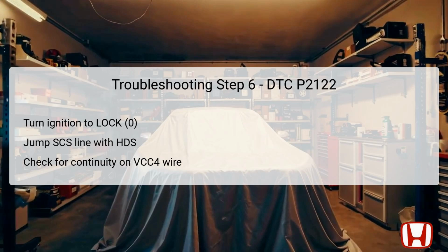Terminal A will be connected to APP sensor 6P, connector number 4, brown, while terminal B connects to body ground. Check for continuity between VCC4 voltage supply points, ensuring that the test conditions match those outlined in the diagnostics. If continuity is confirmed, it indicates proper function of the VCC4 wire, allowing for software update or PCM substitution, and completing repair verification. Otherwise, repair any open wiring faults identified.